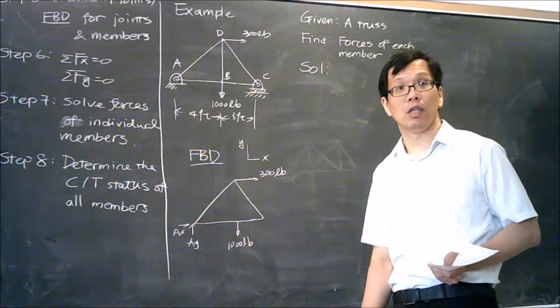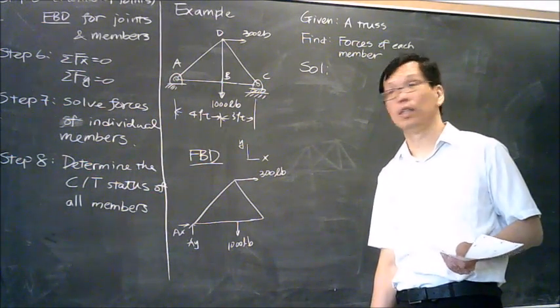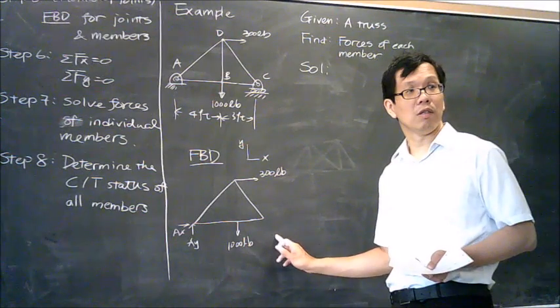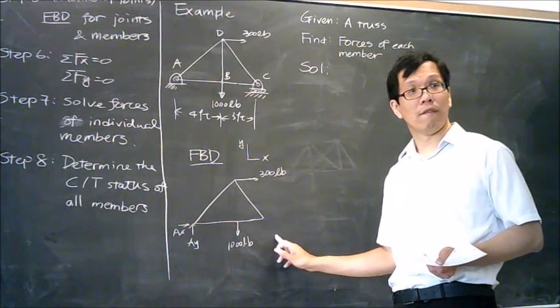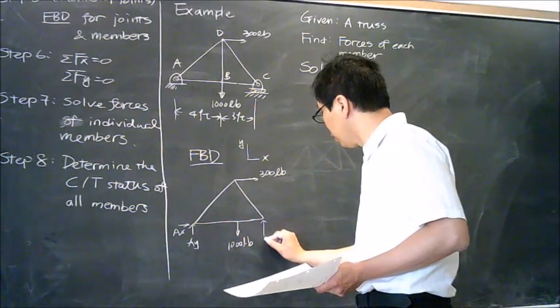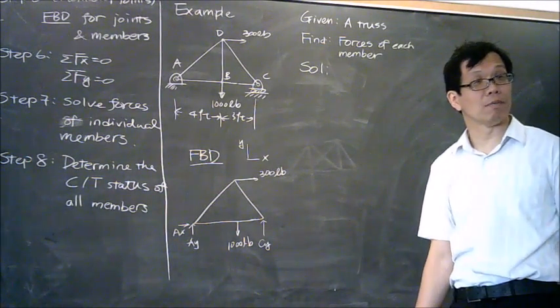How about point C? Am I going to use 1 force, 2 forces, or 2 forces with 1 moment at C? Is the force horizontal or vertical? Okay, it's vertical. So that completes my free body diagram.